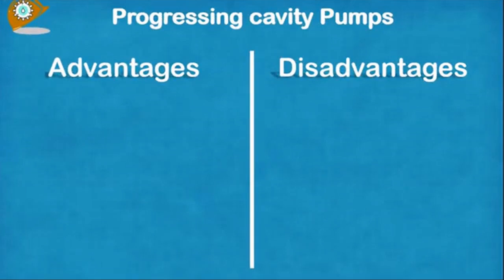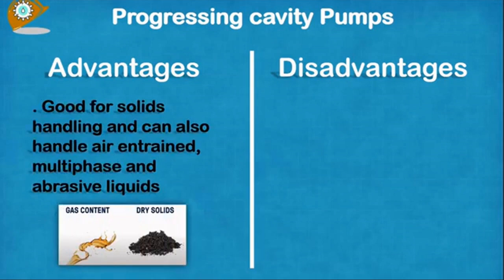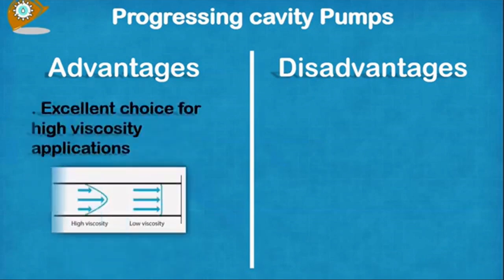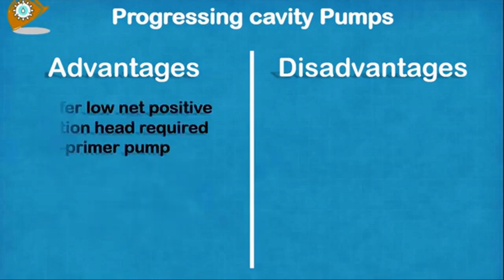Wide fluid handling characteristics make these pumps one of the most adaptable ones available. They can handle viscous liquids, big particles, abrasive materials, fibrous solids, and gas slugs without trouble. There are no comparable pumping technologies since this design has unparalleled viscosity handling, from 1 centistokes to 1 million. Also, it has strong suction capabilities ranging up to 8 meters with a commensurate low NPSH, thanks to the strict tolerances used in its manufacturing.